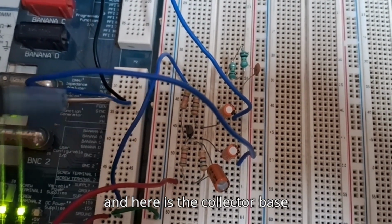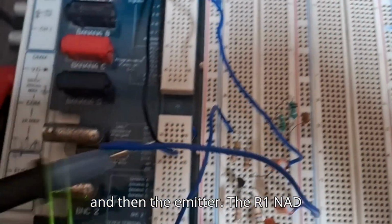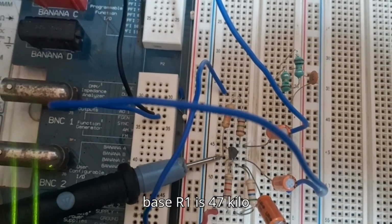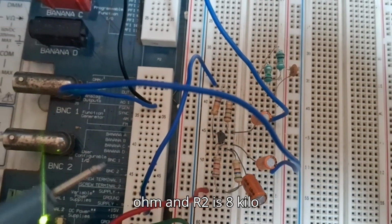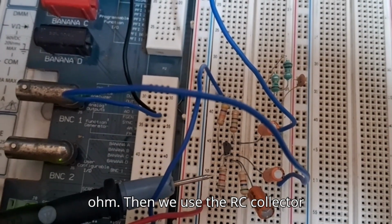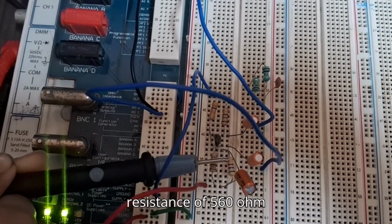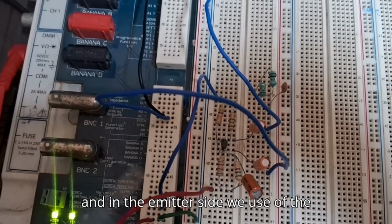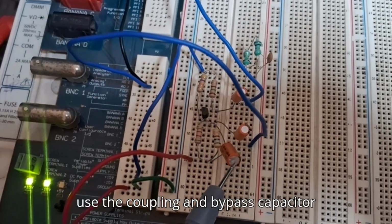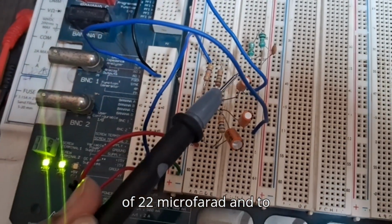Here is the collector, base, and then the emitter. The resistors R1 and R2 are connected to the base. R1 is 47 kilo ohm and R2 is 8 kilo ohm. Then we use the collector resistance RC of 560 ohm, and on the emitter side we use a 150 ohm resistance. And then we use coupling and bypass capacitors of 22 microfarad.